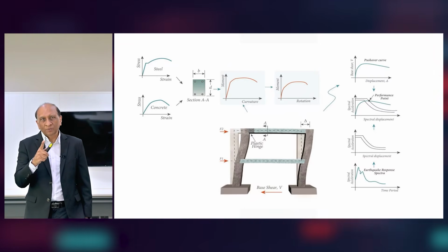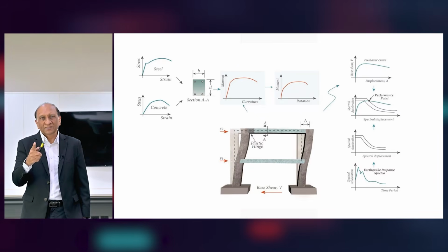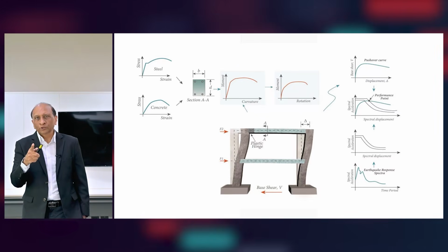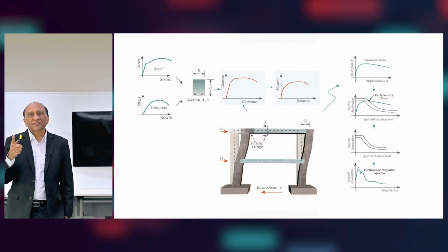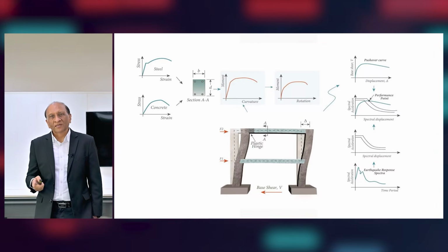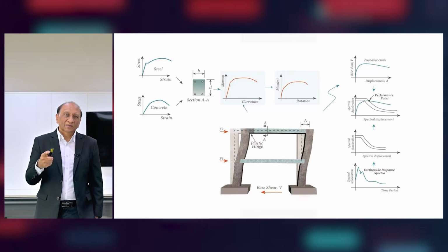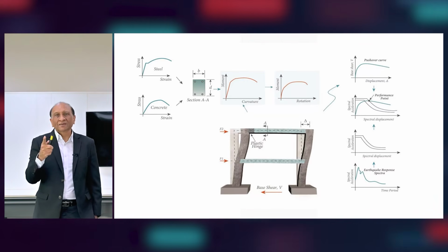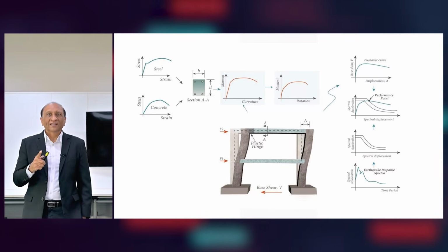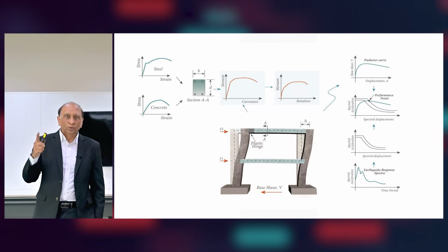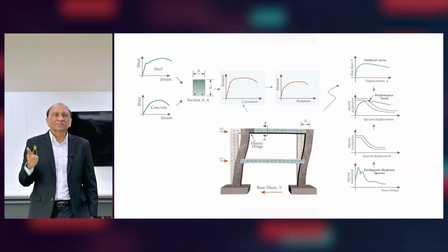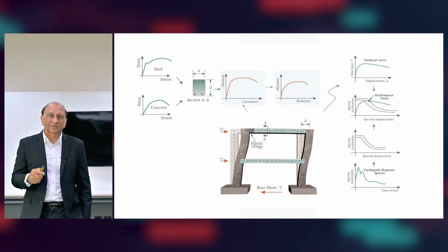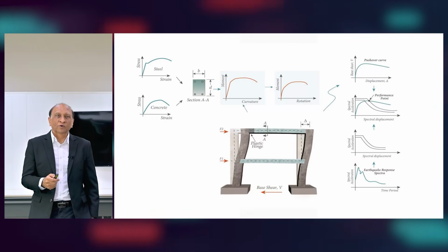gives you the moment-curvature, which gives you the moment-rotation, which is assigned to the plastic hinge, which when done a pushover gives you the ability to calculate the pushover. And from the demand side, the seismic response spectrum can be converted into ADRS, and then we combine them together and we can find the performance point, IO, life safety, and so on. So this is the conceptual framework in which we can see the importance of moment curvature in determining the seismic performance.